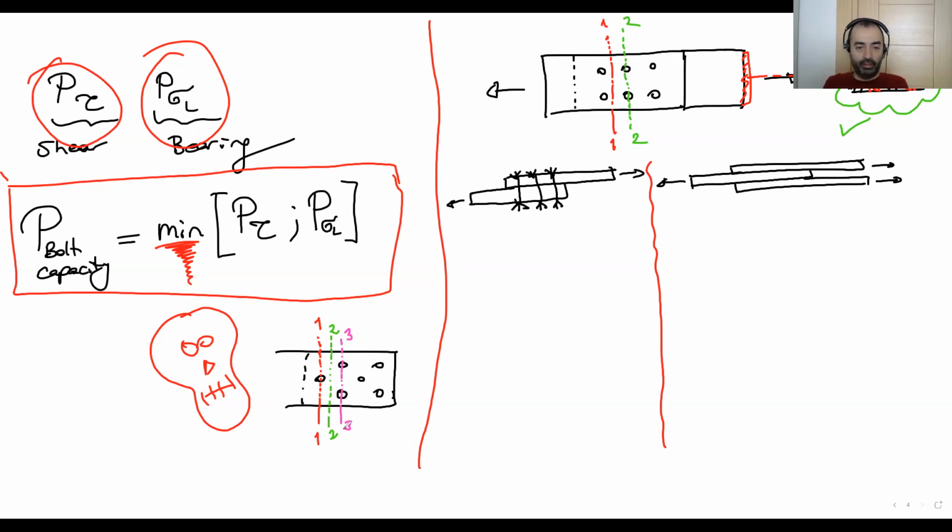Okay, when you compare these three sections, at the end of the day, all of them have a rectangular section. The second one is a solid section. There is no missing area. It's a good section for it. We are looking for the most critical one. That's why we have to find the minimum area on the section. So let's compare the section 1 and 3.